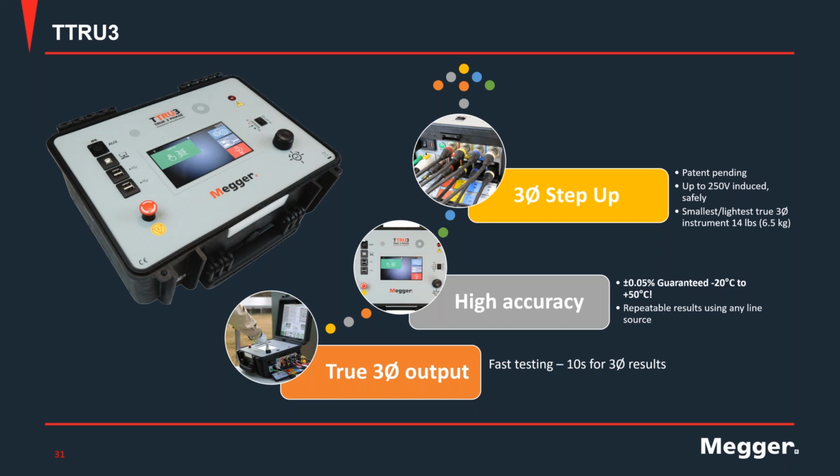And finally, the third major feature is three-phase step-up. It's a patent pending algorithm that will actually perform a step-up test, assuring that the instrument will never have to deal with voltages of more than 250 volts. So the unit will check the ratio of the transformer and then adjust the output. So again, you never will deal with more than 250 volts. It's really important to highlight this. When you want to perform a three-phase step-up measurement, make sure that you have a unit that is capable of performing the test that way.